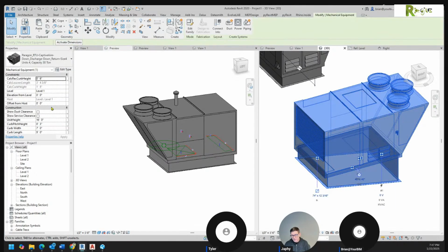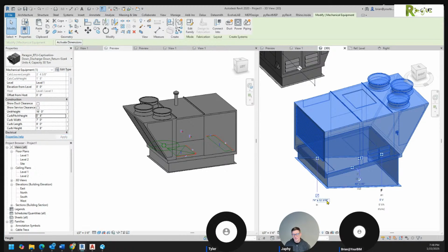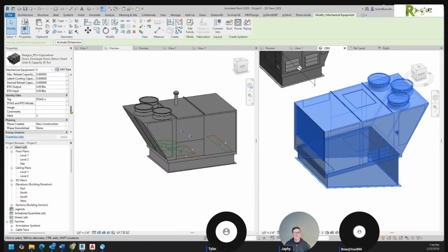Now the curb is pretty doggone cool. It's an instance parameter. So over here, right here's my curb pitch height. See, that allows me to come in here and say this is going on a 4/12 roof. See how it made it a 4/12 pitch? And then on top of that, look at how many parameters. So many doggone parameters. And of course, everything's set for 0.